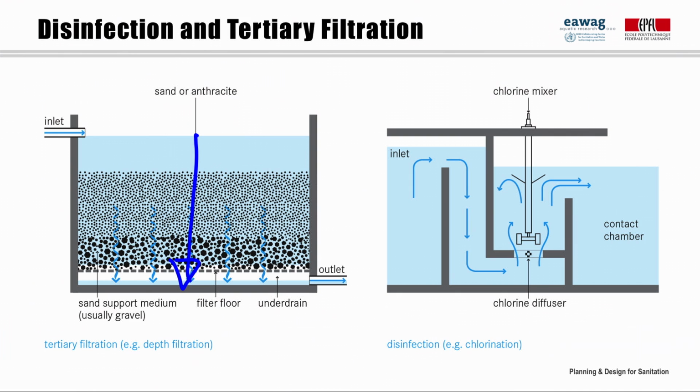However, you have to be cautious with disinfection. For example, chlorine together with organic matter can form toxic byproducts, harmful for the environment. It should thus only be applied if strictly necessary. You don't want to create more problems than you actually solve.